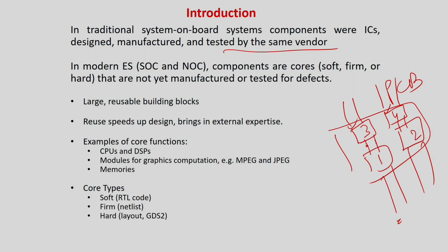Not only that, if I want to test this line, I have to make a multiplexing arrangement, because where I am applying something to this chip, data should not come from here. I have to give some external test data. So, I put a multiplexer, like this is chip 3, and maybe this is your 2:1 multiplexer, this is your test input, this is your normal input, and this is chip 1. So, normally this one will go, and the test mode external input can be given.